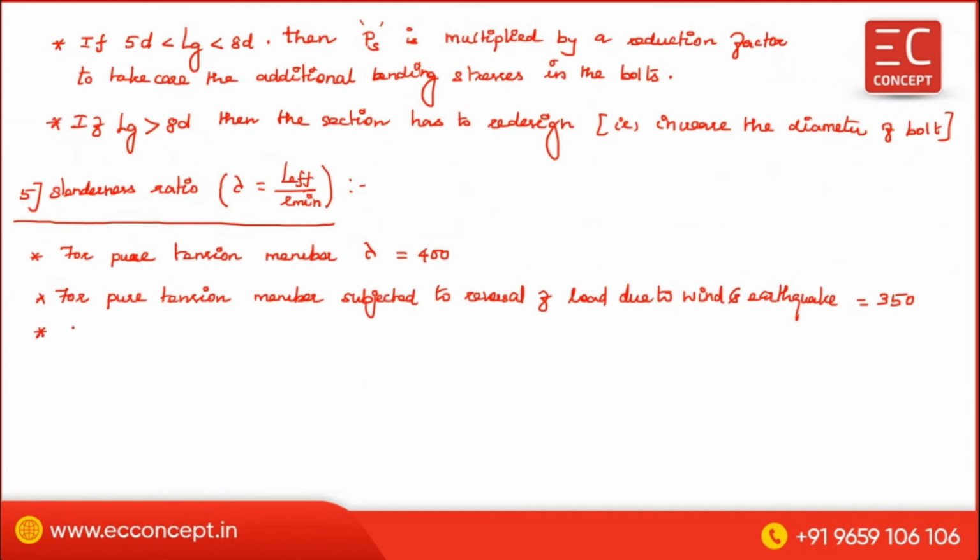Next, for a pure tension member subjected to reversal of load due to live load only, it is equal to 180.